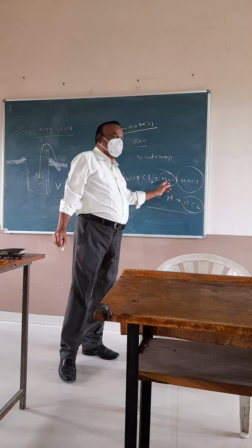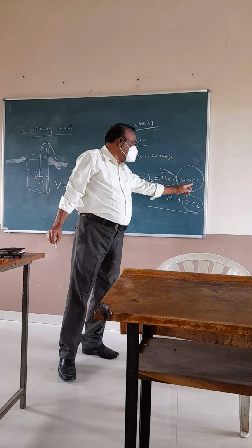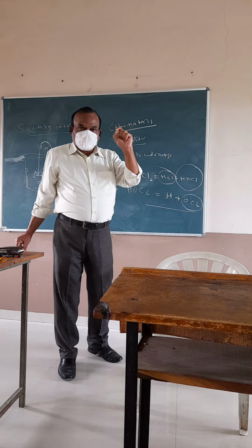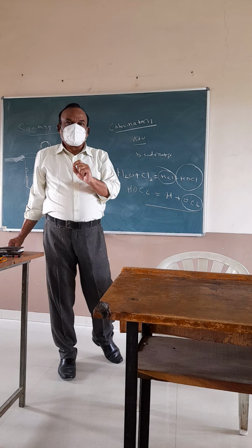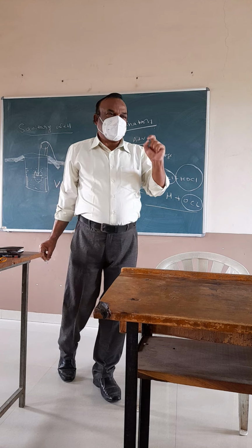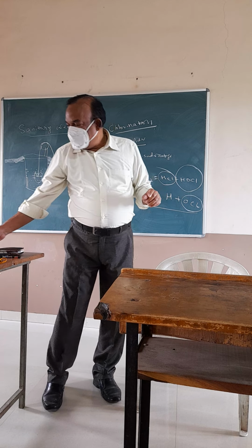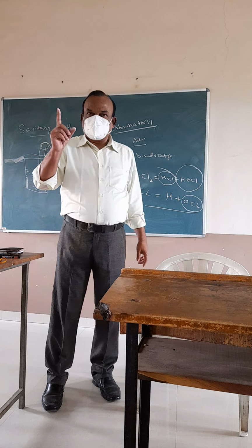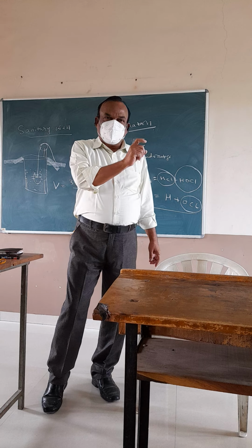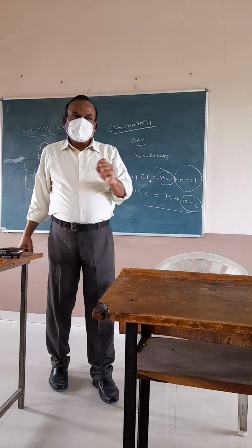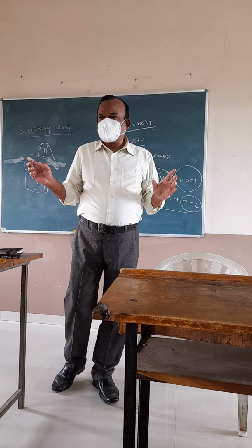This neutralizes the hydrochloric acid. The HOCl causes the disinfection, provided the contact period of the bleaching powder and the water is 1 hour. When this chemical reaction occurs, free chlorine is released, which is very unstable.